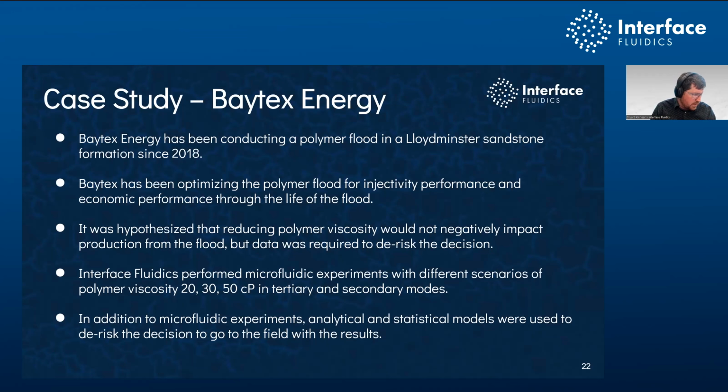So first question is how to customize the permeability of microfluidics, typically higher than rock cores. I would say that that's not an accurate expectation. We create systems that have the same permeabilities as the real rock. We've created everything from nano-Darcy permeable systems for unconventional reservoirs, all the way up to multiple Darcy systems for conventional, and everything in between. So there's really no limitation on permeability that we can create.